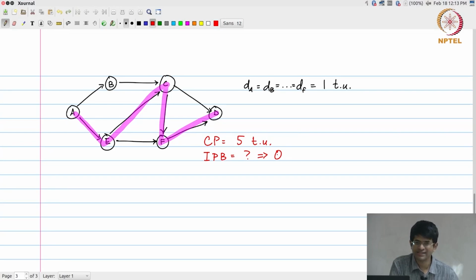So one way of looking at that is A by itself imposes a loop, right. I can think of it basically as having a self loop over here with one delay element, saying that only after A has finished once, it can then start again on the next iteration. And if I had this kind of a self loop on each and every one of my operations, or my hardware units.